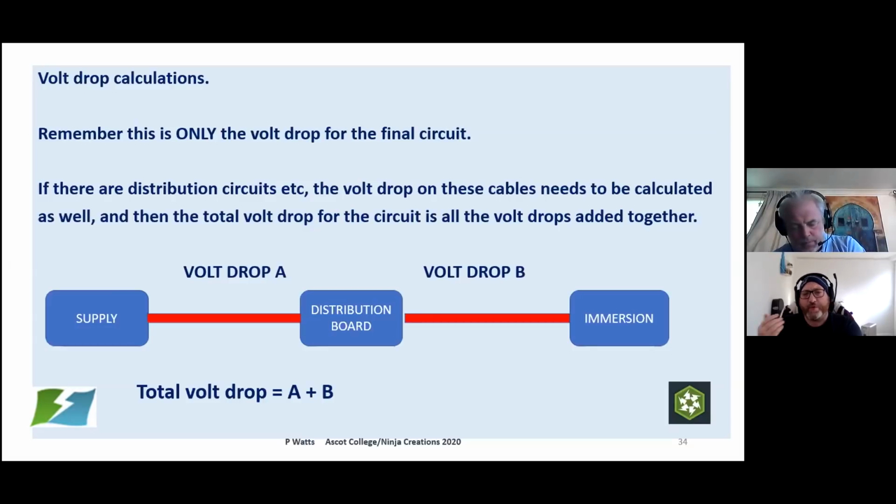This again goes to the point of the initial verification, and that key word, which we don't cover enough, is functionality. We've done it in the previous webinar. We said there's a functionality box for our RCDs and AFDDs. But what about everything else which requires verification of function, especially on initial verification where it's fresh out the box? I've had MCBs fail. I've had sockets fail.